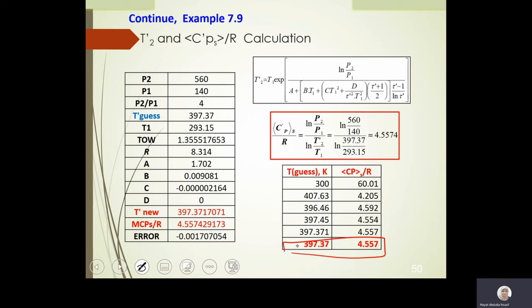All right. So what I did then, I just calculated delta H dash. But remember, for this delta H dash, you need T2 dash, which we calculated. CP mean dash H, you need T2 dash and T1. So it's just direct substitution, and this will enable us to get the delta H. And see how this delta H dash is useful. It's very useful because I will need it to relate actual with isentropic conditions through the efficiency. So I took this value, I divided it by the efficiency to get the actual, and this is what they need in the question. They need the actual work.